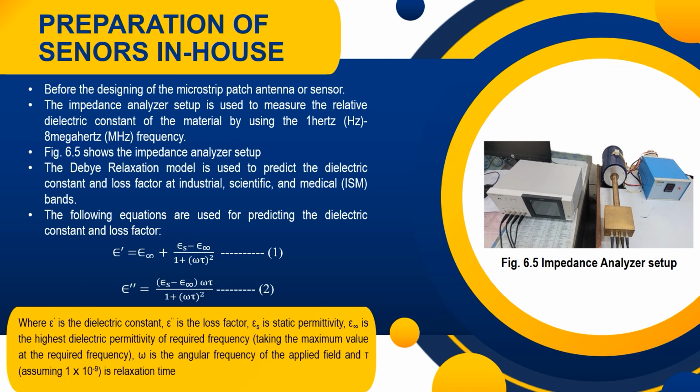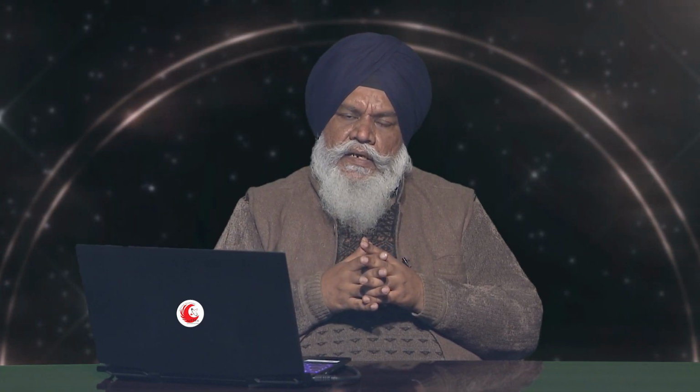So for that purpose, one of the basic instruments in front of you is called an impedance analyzer. We use this system, available in our lab, and it can give me information about the dielectric behavior up to 8 megahertz. There are high-range impedance analyzers that can give output in the range of gigahertz, or sometimes terahertz. But for simple applications, for a low-cost or lab-like solution, we normally have input from kilohertz to the megahertz range.